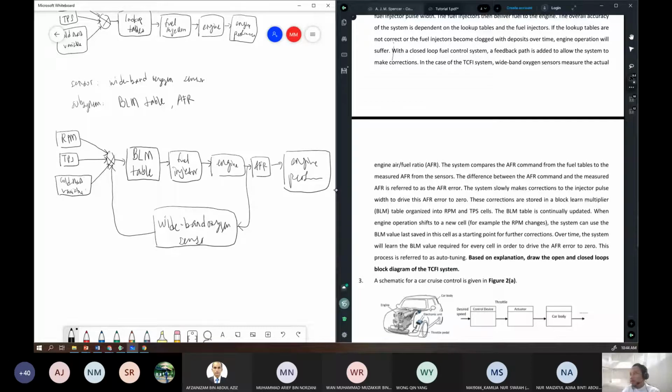So the second part, the closed loop, is something like this. Okay. So now I hope you understand that open loop is always in a straight block diagram configuration, while for closed loop system, we have a feedback, a sensor, and a comparator or a circle with cross, and then usually followed by an additional controller.